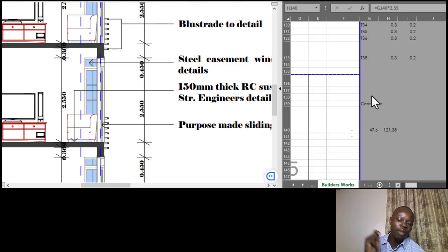But when they are not given, the alternative is that you are always allowed to use what we call standard sizes, which sometimes doesn't apply. Sometimes it doesn't apply for the windows, but it might apply for the doors. Depending on where you are, maybe you can take the doors as 900 by 2400, so you can always subtract those areas as a standard for the doors.